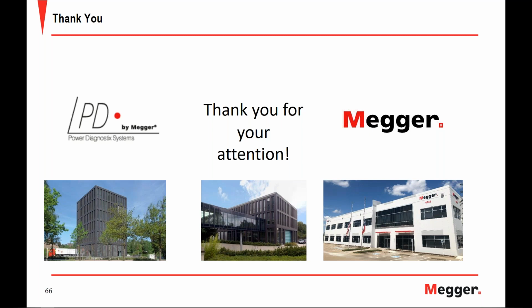Is offline PD measurement applicable for 4,000 volt motors? Well, Michael, that's a good question. In the literature, there's a lot of information going around that PD measurements are only suitable for machines with a rated voltage of 3 kV and higher, because basically they're considering the inception voltage being 3 or 2.7 kV a centimeter at atmospheric conditions.